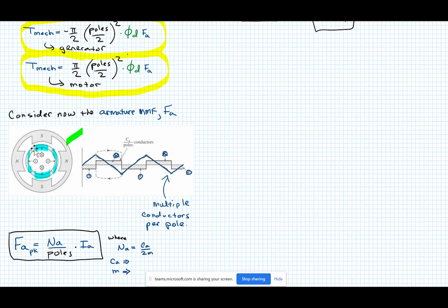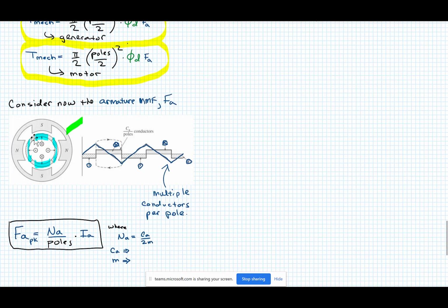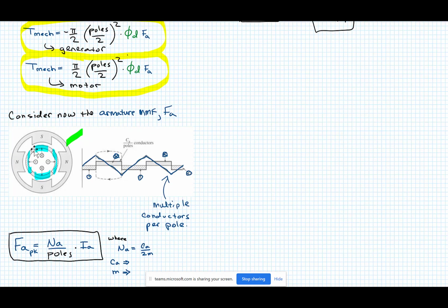But from a real analytical standpoint, to try to understand the MMF, you can think of it as a current sheet, a sheet of MMF that just flips direction as the rotor moves. If you add more turns and more segments, it actually starts to become triangular. I'm not going to go over this again.